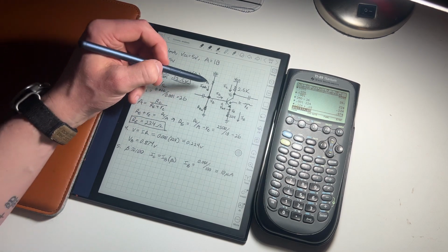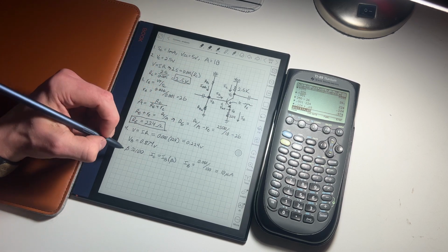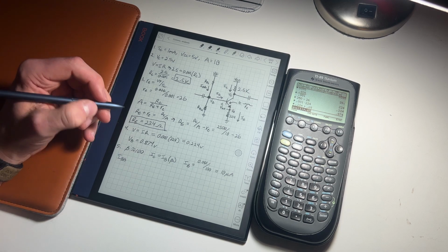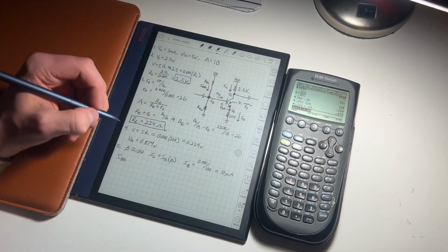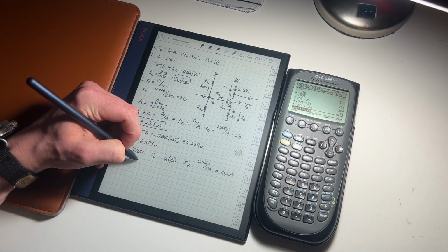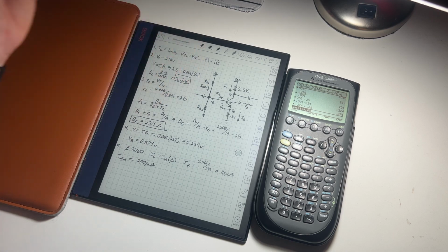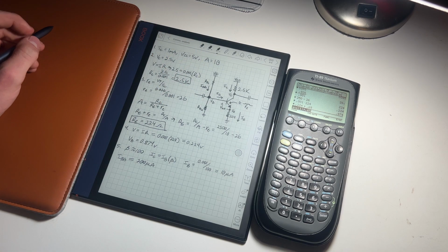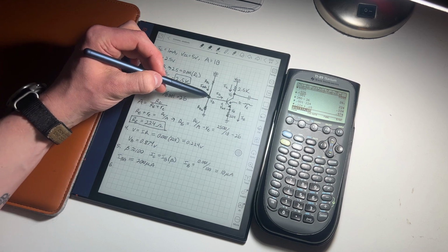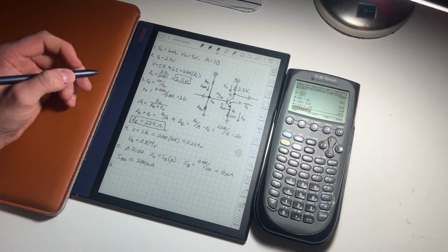So, in order to set up this voltage divider and to have a stable bias voltage, we want IBB, or the base bias current, to be equal to around 20 times this. So this is going to be equal to 200 microamps of current flowing through these two resistors. So, steps 6 and 7: we know the voltage here, and we know the current flowing through both of these resistors, so we can solve for these resistors.